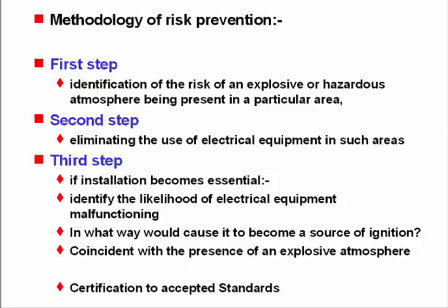And each potentially explosive atmosphere has several different characteristics. Some of it can be easily ignited by a hot surface. All the gases have different auto-ignition temperatures, and a lot of them have different ignition energies. So we need to make sure that the equipment we purchase and install is suitable for our particular hazard. We've also got to consider the risks of the electrical equipment either malfunctioning or being operated beyond its normal manufacturer's rating. So of course, the ignition also needs to be coincident with the presence of the explosive atmosphere being present at the time. So there's a degree of risk assessment as to the probability that the gas is there, and we'll be looking at that when we look at area classification.